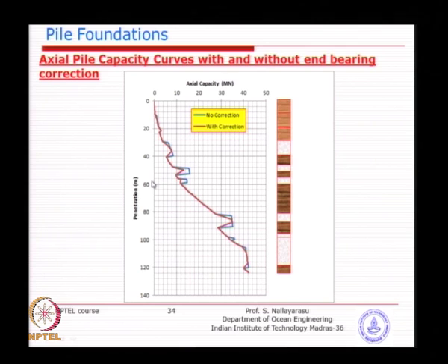So, you can develop this without needing to know the penetration in advance. What you need is a diameter, definitely you need a diameter. So, for every penetration you assume, you calculate and then relate that. This graph is very useful, and most of the time it will be available from the geotechnical report, where somebody has come up with borehole information. The only problem is that perhaps only a particular diameter is given, because they will not know what diameter you will come up with. So, that is the time you may have to generate more diameters.